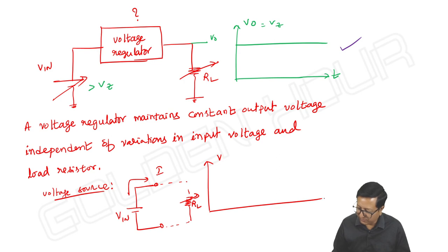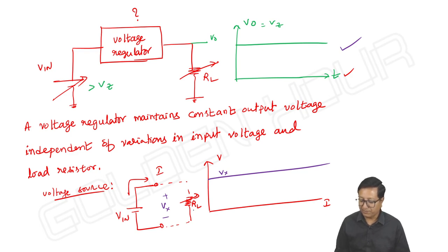the value of RL, if I take VI characteristics, it's voltage with respect to time. Here I am writing voltage with respect to current. It maintains constant voltage, ideal characteristics I am writing, right? It is maintaining constant voltage V or Vx, let it be, right? I can write Vx is the value with different current values. The current depends upon RL, current is equal to Vx by RL. Depending upon RL, the current value will keep on changing. Ideal characteristics of voltage source.